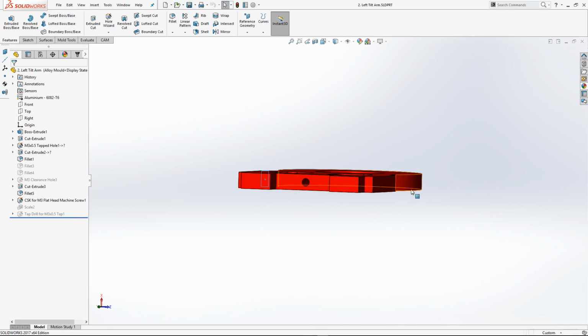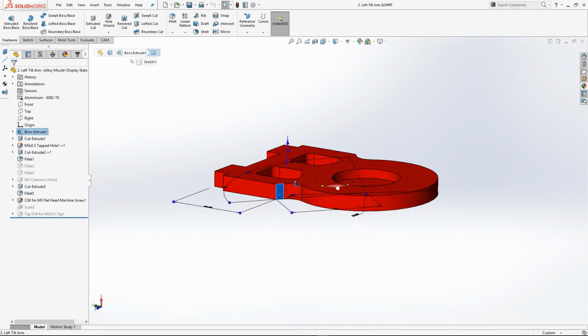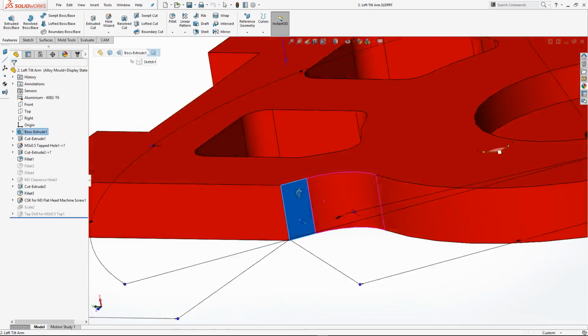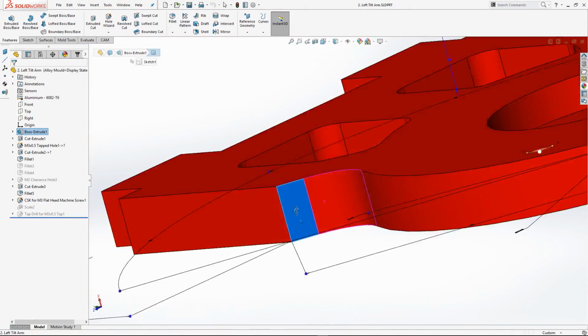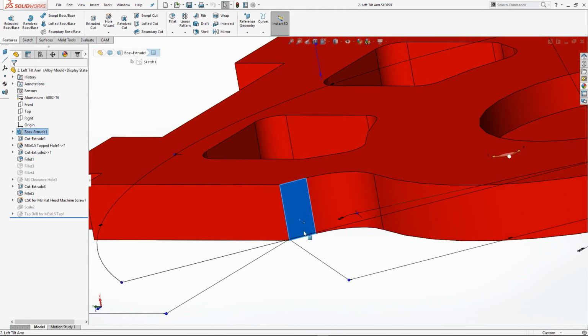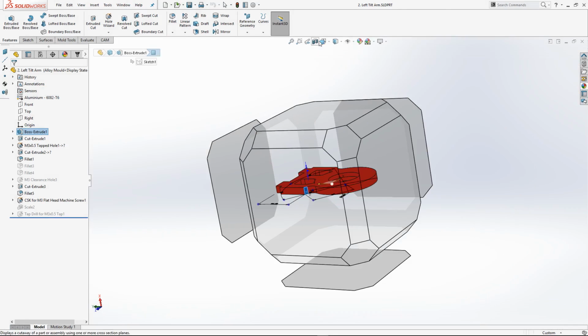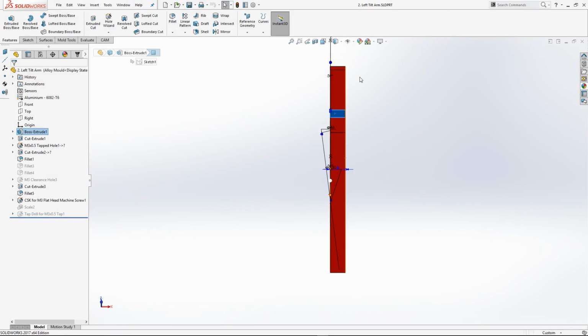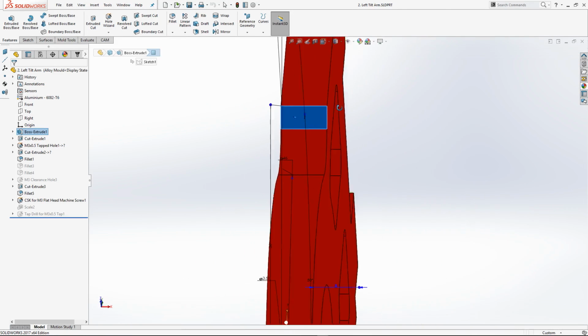If you want to design something, or you want to do an extrude on this face, for instance, it can be a bit of a nightmare to get it in the orientation that you want it in when you're doing the sketch. What you can do is click the face you want the view on, and then click this little up arrow here, and it'll bring you on that face, so you're actually looking directly at it.